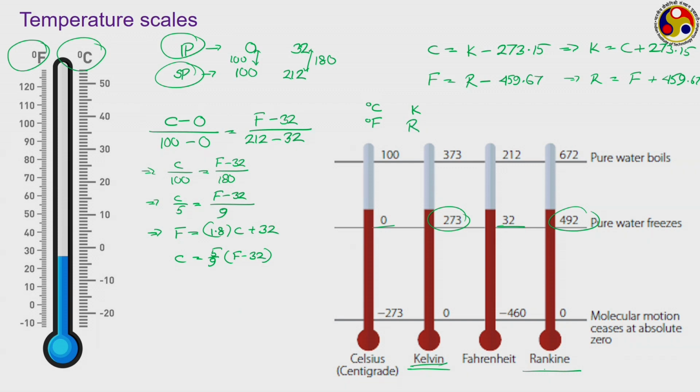So, these are the most common temperature scales that we can think of. However, as I have mentioned, you can easily define any 2 point temperature scale by choosing your own values at ice point and steam point, and then taking an equal number of divisions in between the two. Then subsequently you can extend in either direction, that is below the ice point or above the steam point, just following the same pattern of the subdivisions.